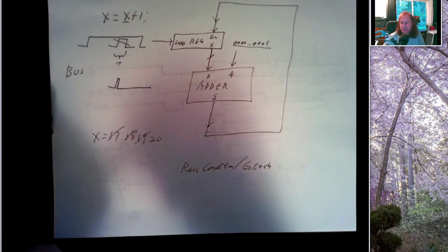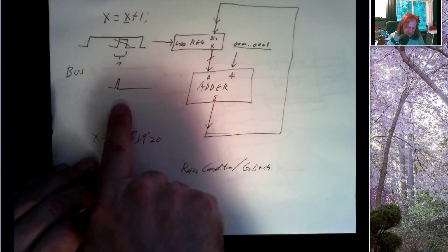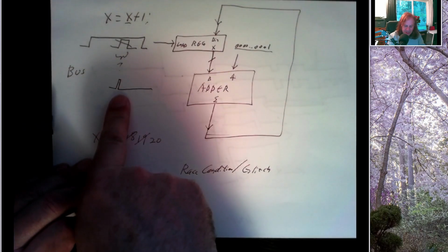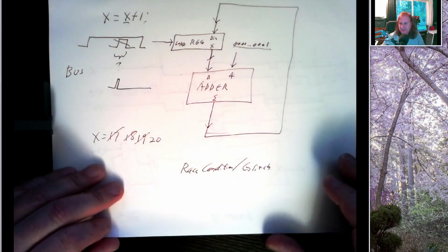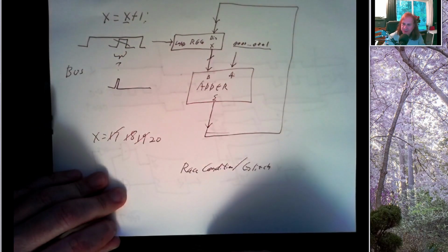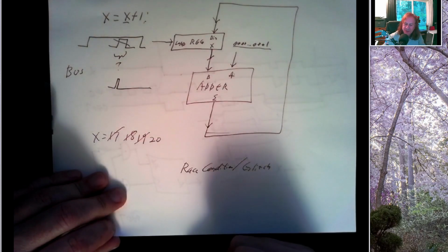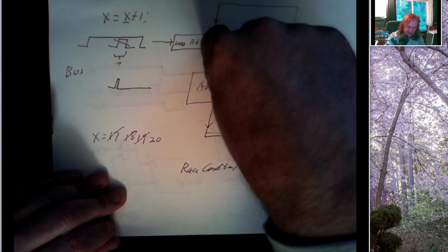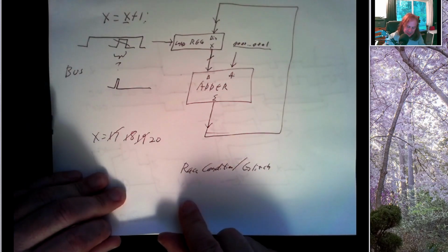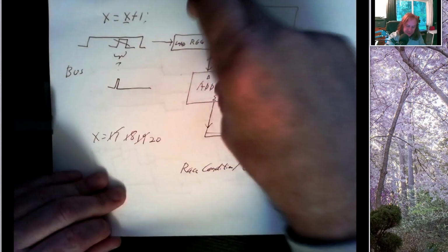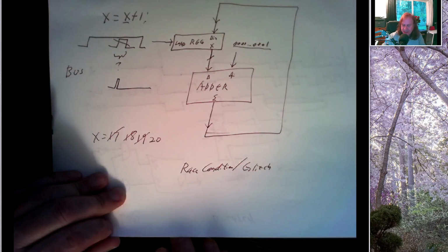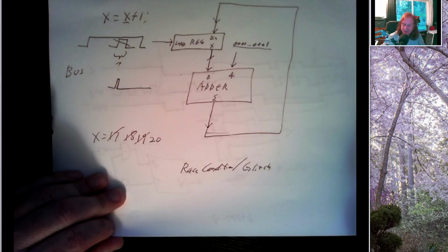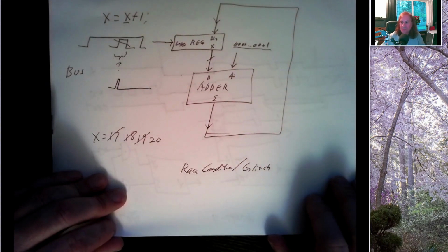Where the behavior of the circuit depends very, very critically on the timing of this load signal, as well as the physical characteristics of these devices, how quickly they respond, which, by the way, depends on things like what the temperature in the room is. And if I do this in a room that's heavily air-conditioned, or I do it in an un-air-conditioned lab in the middle of summer, I'm going to get different behavior out of this. And that's just a nightmare to try to design around. If you have to design a circuit and it can only work at a certain temperature and with certain controls on the voltage going in and certain relative humidity and only with a certain probability, that's just a nightmare.